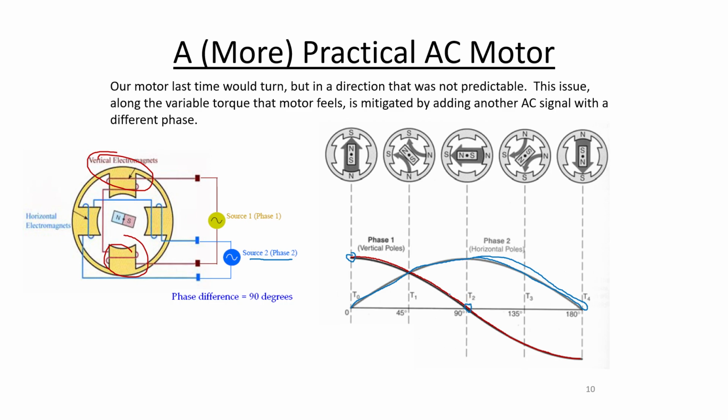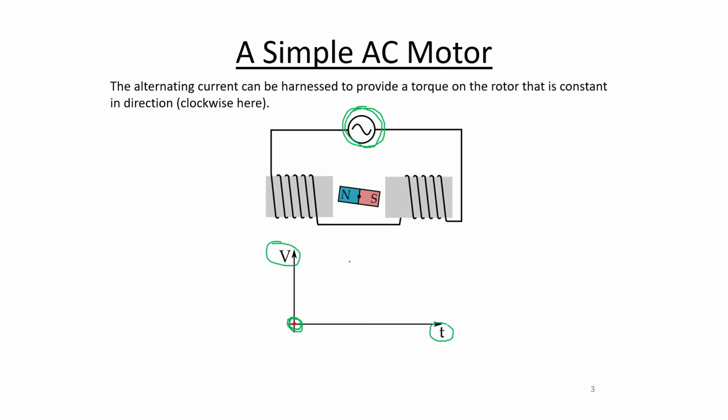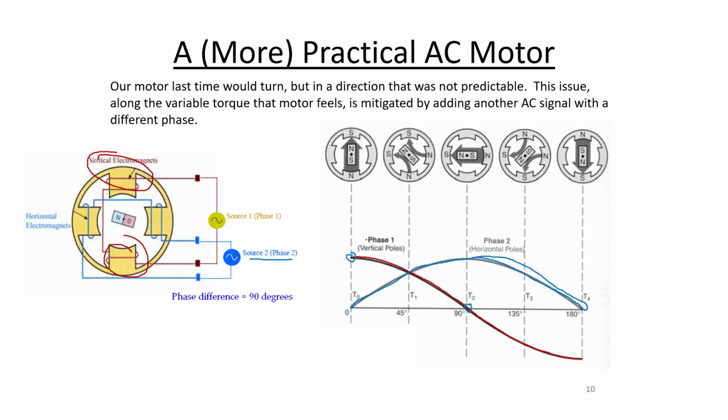The thing that this buys us in an AC motor is that you'll remember way back at the beginning of this thing, I gave this rotor just a little bit of tilt. It's not straight across, it's just tilted just a little bit, and that's so that when the voltage starts to rise and the current starts to rise, then you get this clockwise rotation. Right? If I had started this the other way, like if I had tilted it so that it was like that, for instance, well, then you would get rotation in the opposite direction, and there's really no way to control that in this kind of motor except by where you start the rotor position.